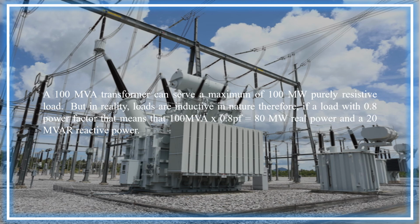For example, a 100 megavolt-ampere transformer can serve a maximum of 100 megawatts purely resistive load. So, as I said earlier, loads are inductive in nature. Therefore, for a load with 0.8 power factor, that means that 100 megavolt-amperes has to be multiplied with the power factor 0.8. So it equals 80 megawatts real power and 20 megavolt-amperes reactive power.